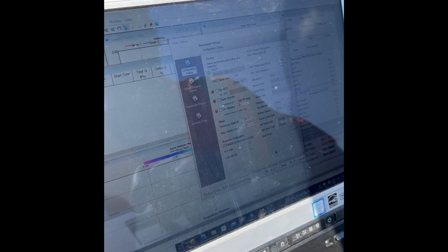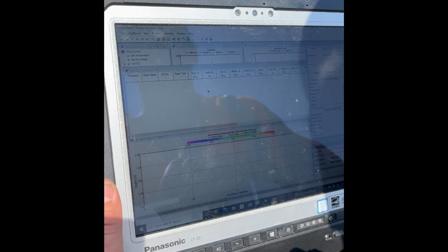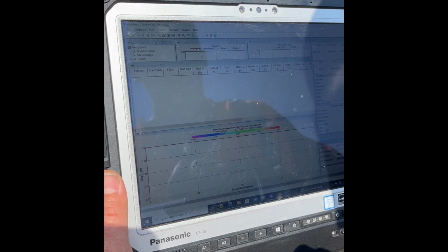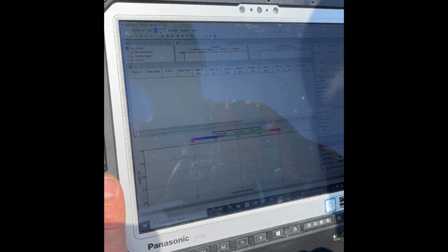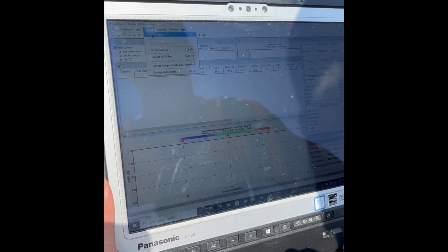The thing that benefits from this is the number of cells and the cell size that is given to the ADCP. Since there will be smaller cell sizes, we'll have more cells, making it a little bit more accurate. It also makes it so that we can get further in on the banks, as we need 2 cells on each side. And if our cells are too big, we can't get as close to the bank. So now we'll start up the pinging again.